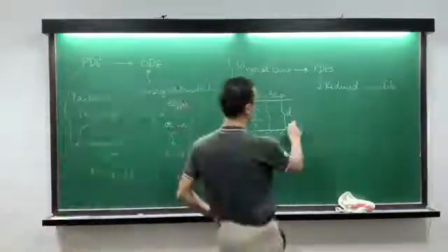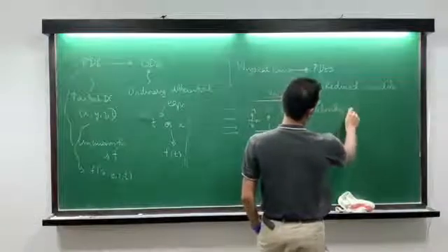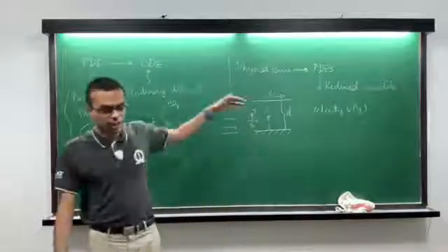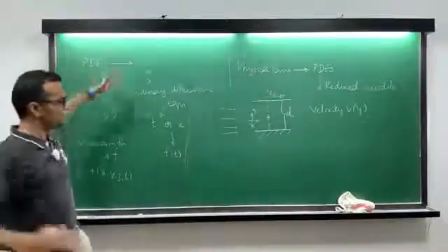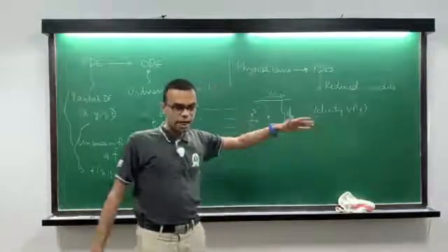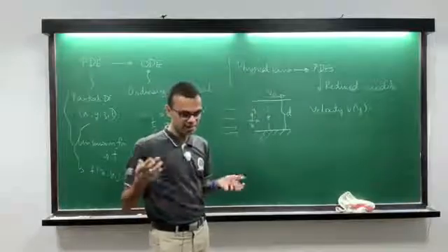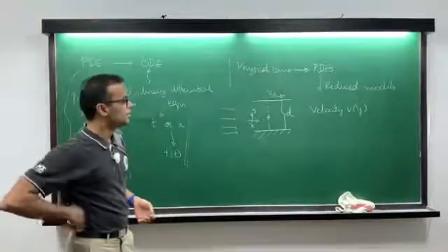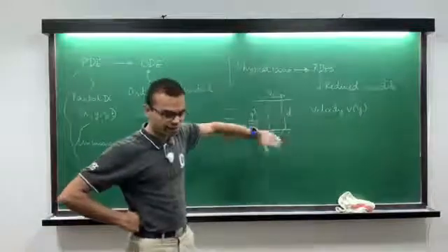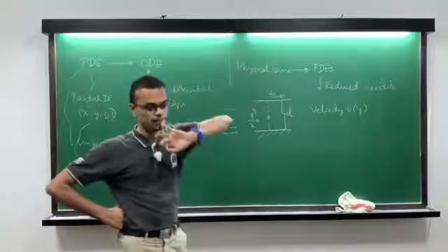So then I'm going to ask for the velocity profile v as a function of y alone. It's an infinite plate, so as t goes to infinity, presumably the velocity profile should not depend on x, and because t goes to infinity, if it reaches some type of steady state, again that's a phrase you will hear often, then the velocity should depend only on y. Of course, the gradient in y will never go away because the bottom plate is always fixed, and the top plate is always moving with a velocity v naught.